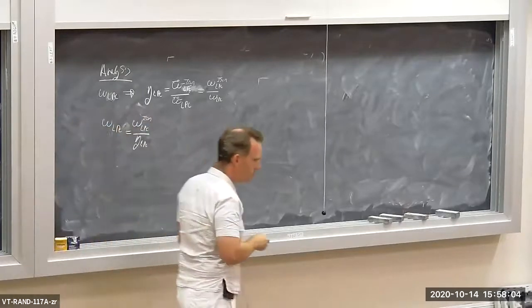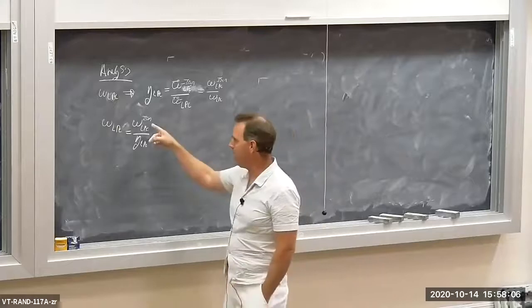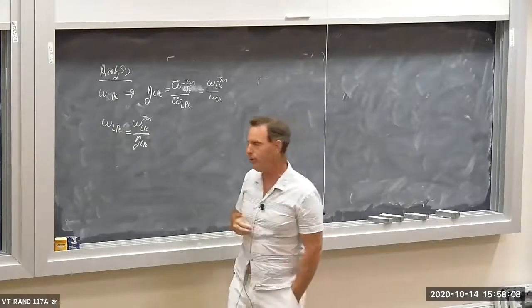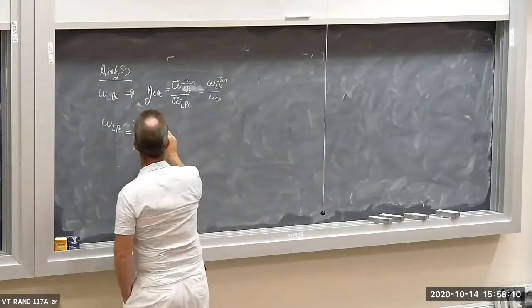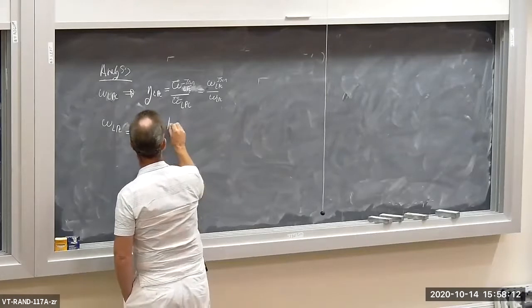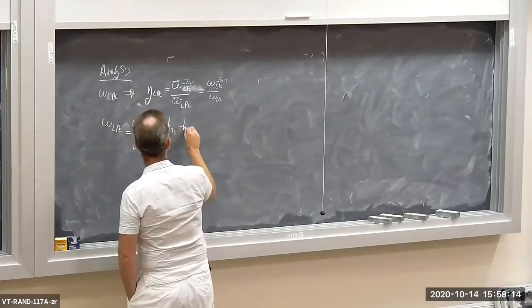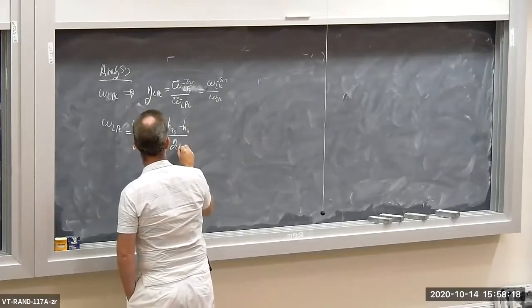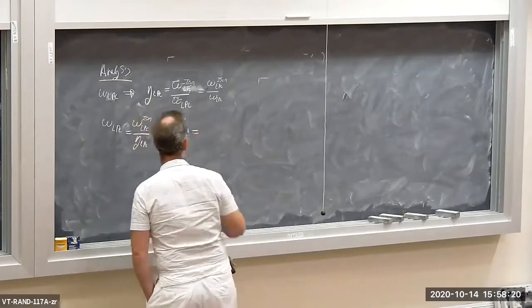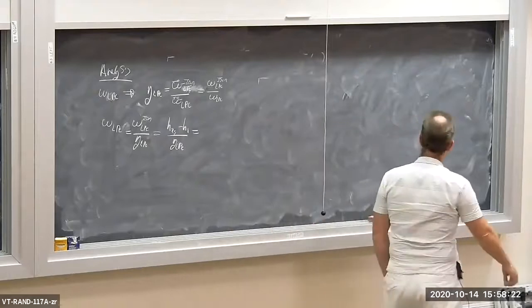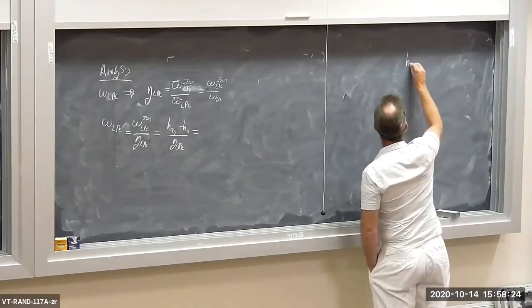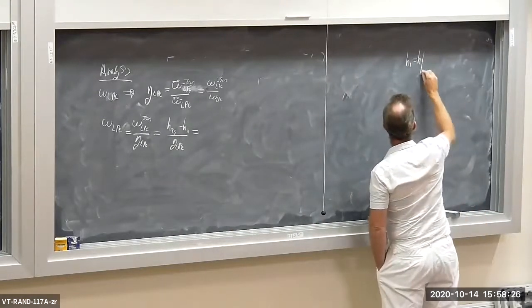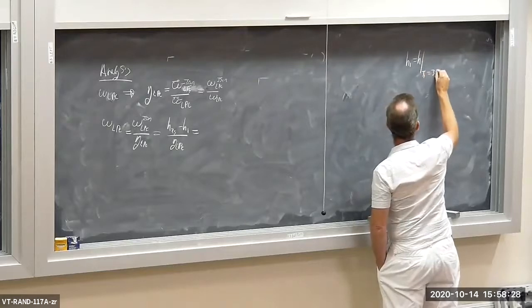Okay? Now, if you apply the energy balance to the isentropic compression process, you'll get h2s minus h1, again divided by eta_LPC. Now, h1 is going to be h evaluated at T1, which is 300 degrees Kelvin?